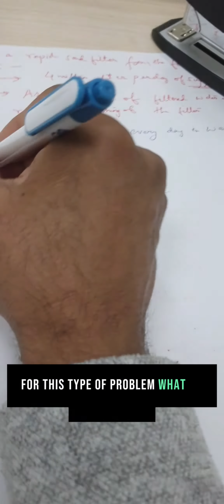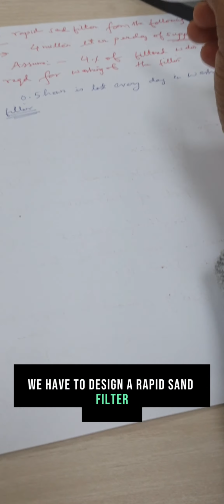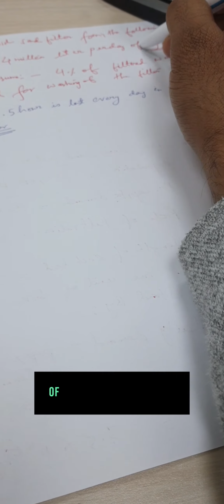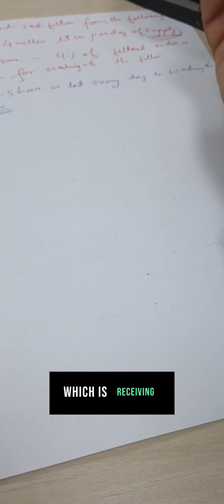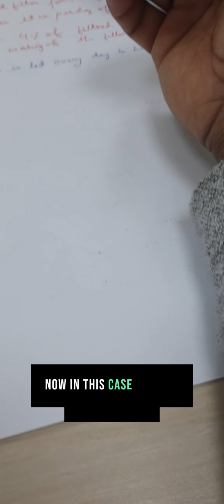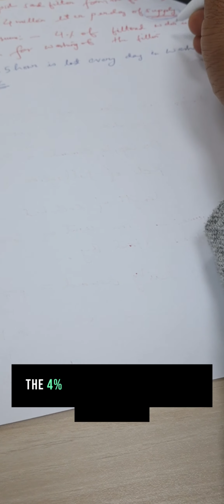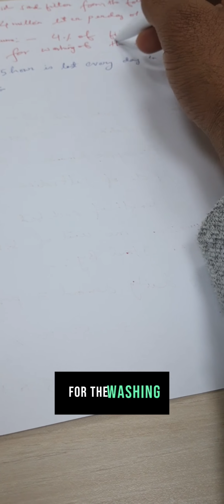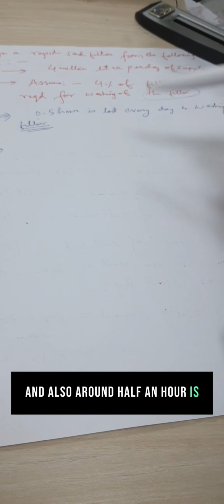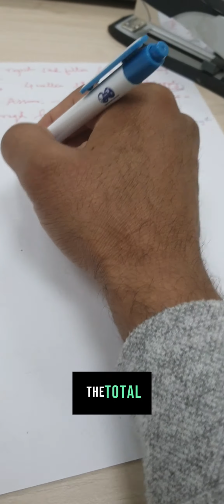For this type of problem, first of all, the data given here is that we have to design a rapid sand filter, which is treating around 4 million liters per day of water supply. Basically it will be treating this much amount of water. Now in this question, certain assumptions have to be made. We are assuming that 4% of the filtered water is required for the washing. So this is the case of backwashing, and also around half an hour is lost every day in washing the filter.